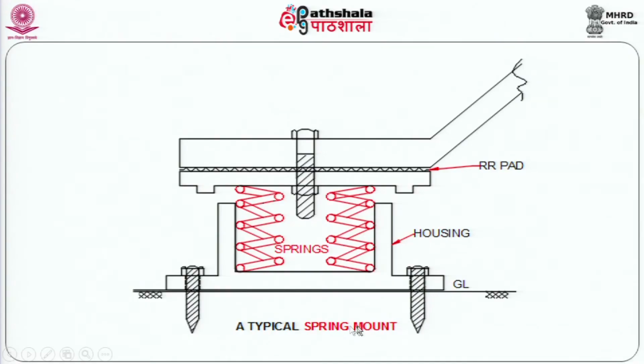As the word restraint implies, after that point the equipment will not stop the vibration, but it will stop itself from collapse. So, after the earthquake is cleared, you can perhaps replace the AV mount and you are back to square one without any problem. Now, this is a feature where you will see the AV mount, these red items are the springs. Now, this is the seismic constraint.